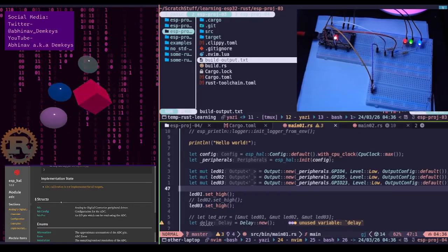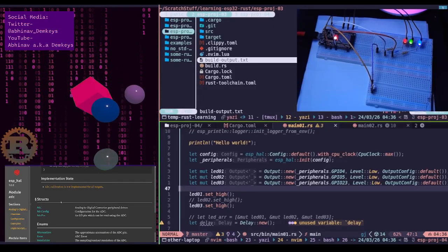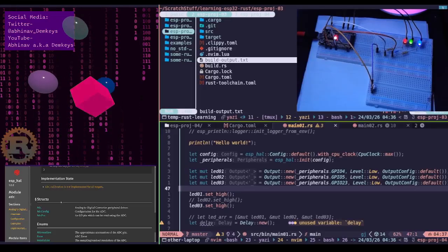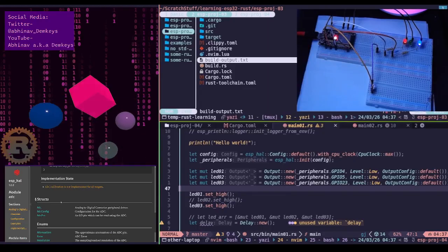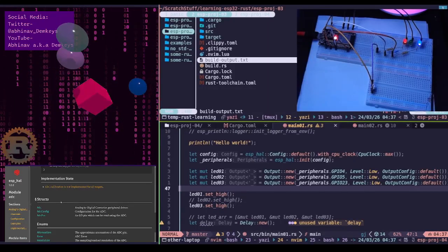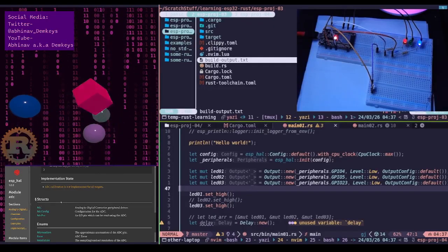You might think, can a voltage divider give my LED exactly 2 volts? The answer is usually no. If you connect a load like an LED to the middle of the voltage divider, the LED acts like a third resistor in parallel with R2.